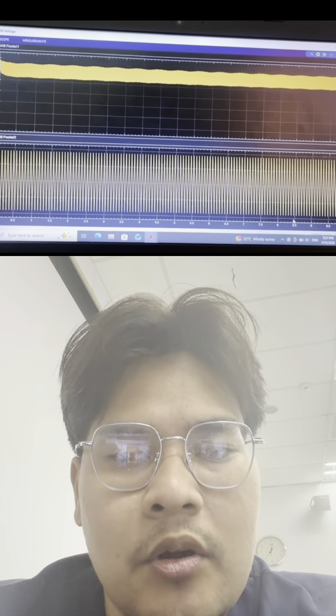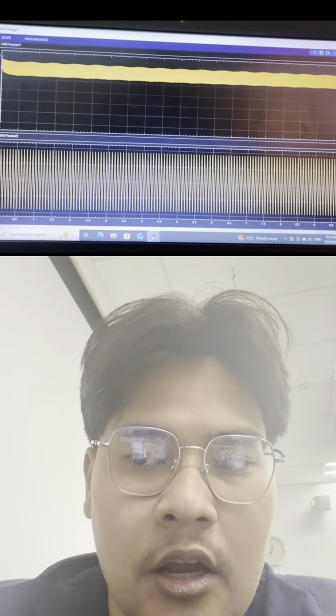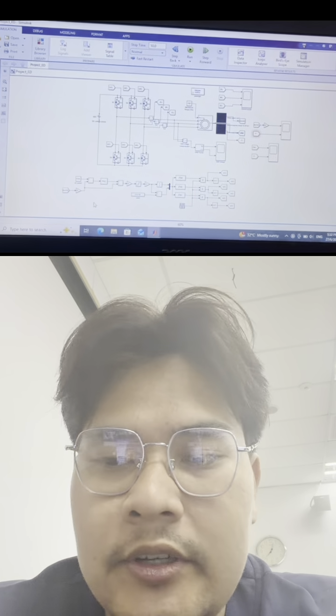undergoes initial startup oscillations matching our inrush currents. However, it rapidly stabilizes exactly at negative 100 Newton meters. This perfect balance confirms that the motor has achieved dynamic equilibrium with the load. On the bottom axis, the rotor angle shows a flawless, uniform sawtooth pattern because the speed is perfectly constant. The angle repeatedly cycles from 0 to 2 pi radians without any distortions.